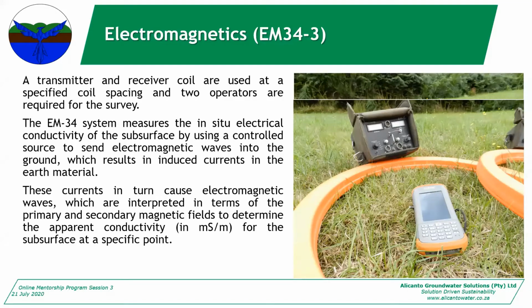Yeah, you see, the thing is, you don't actually pick up water. That's what I was saying right in the beginning. You're picking up your potentially groundwater bearing fractures or contact zones. So you'll see an increase in conductivity. We'll go through the different anomalies and the shapes and all those kind of things during this presentation. But you don't pick up water unless you've got a clay or something.